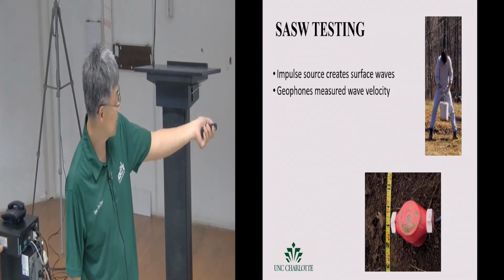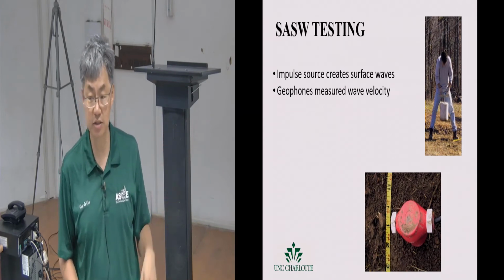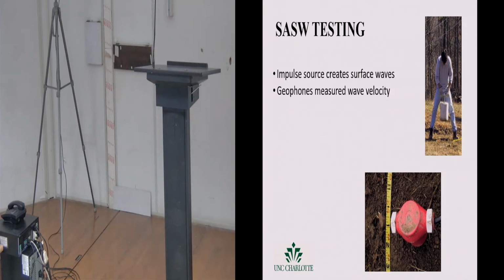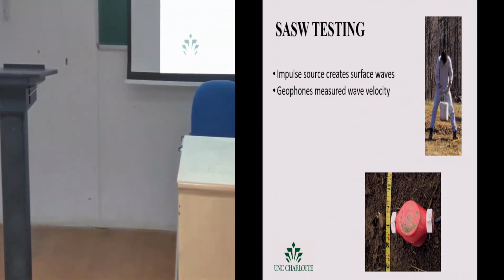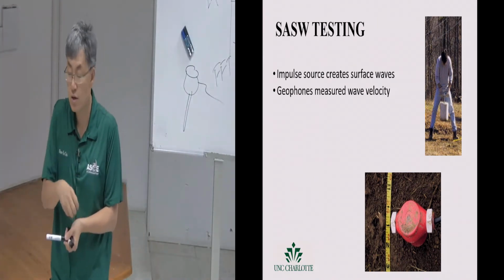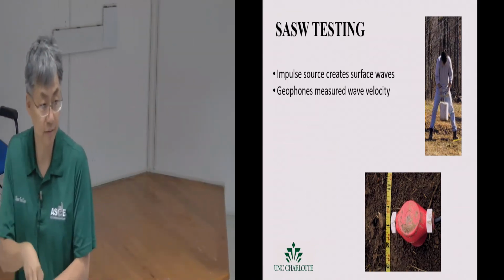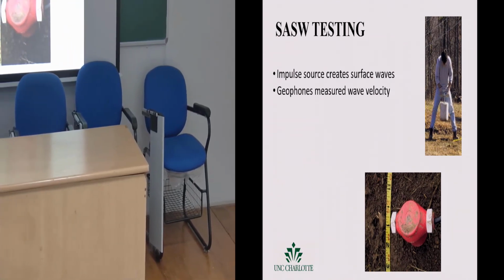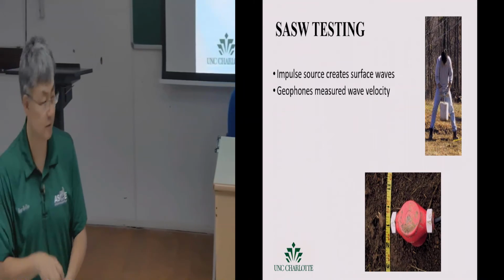Yeah. This is the sensor on the ground. Okay, so when you do this kind of study, it's not exposed, but this sensor actually has a needle underneath. A spike. So the reason is because the ground is soft. Okay, if you just put it on the surface, when you do vibration, the sensor will separate and bounce, and then the signal will be useless. So it has to be closely in contact. Okay, so for any sensor, the important thing is the contact. Okay, that's why we go into remote sensing, because you don't worry about the contact. But using this kind of traditional sensor, you have to make sure they have full contact.